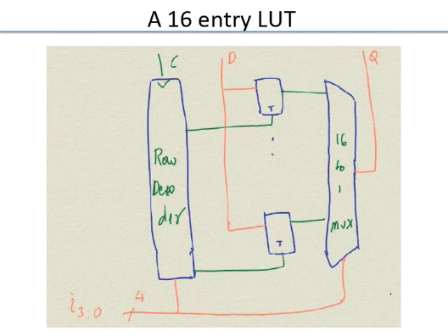So this is a very simple structure, right? It's just a mux. Now, if you had something more complicated, which we'll see next, with sense amps and so on, then there's no need to activate all that circuitry because you're just wasting power. Similarly, here, if you don't want to waste the power to drive this, you might want to disable that by ANDing it.